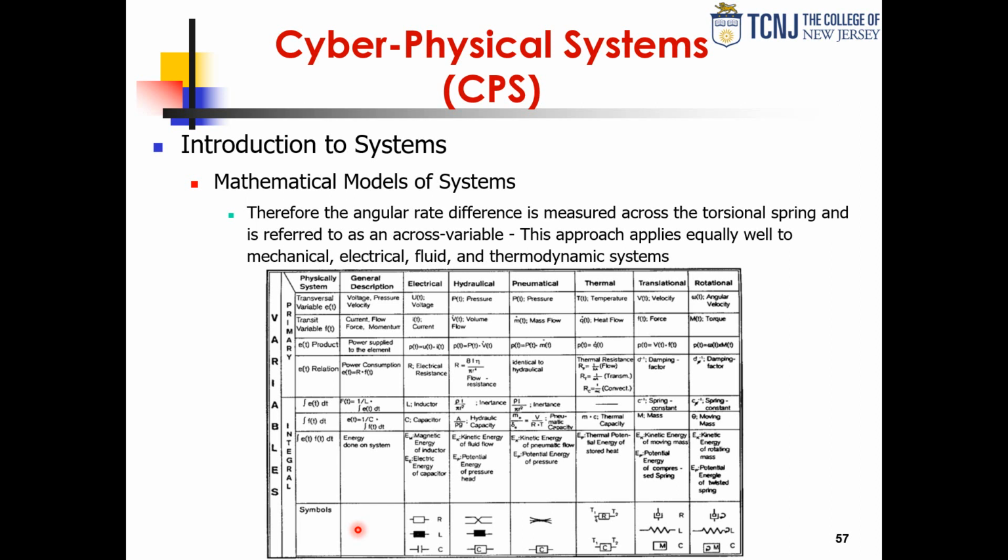There are equations to translate from thermal to electrical, do the analysis, get the results. A current is sort of like a heat flow. A voltage is sort of like a thermal gradient, and then you convert back, and you have done, in a roundabout way, your thermal analysis. So it's a trick of the trade, if you will.